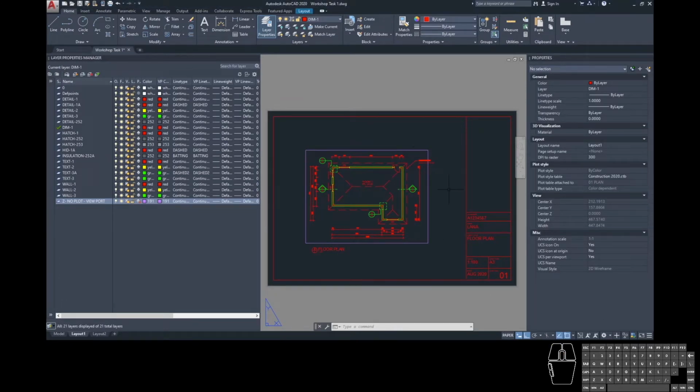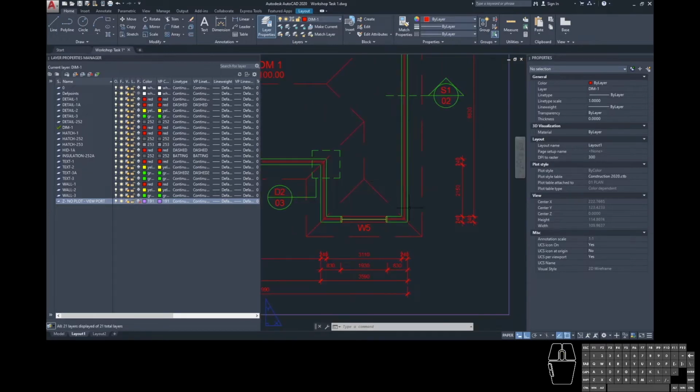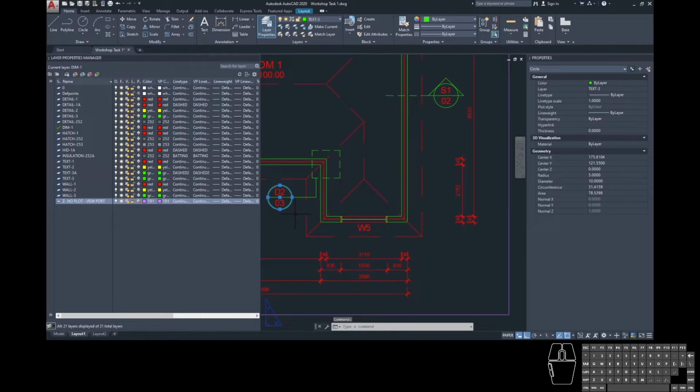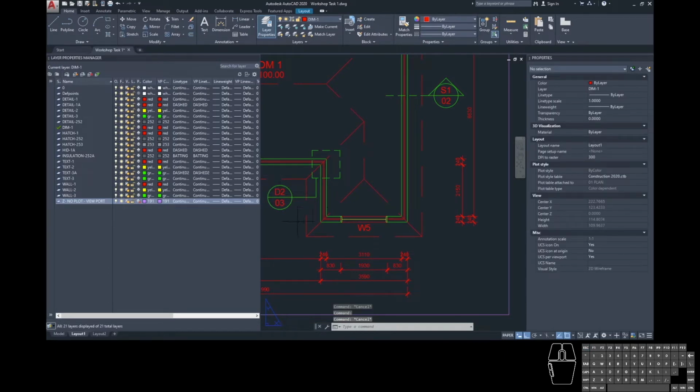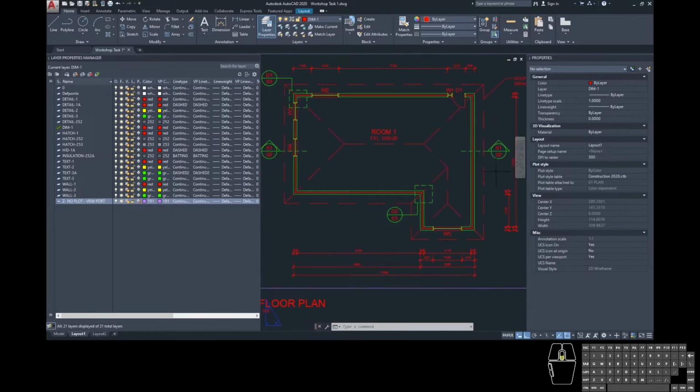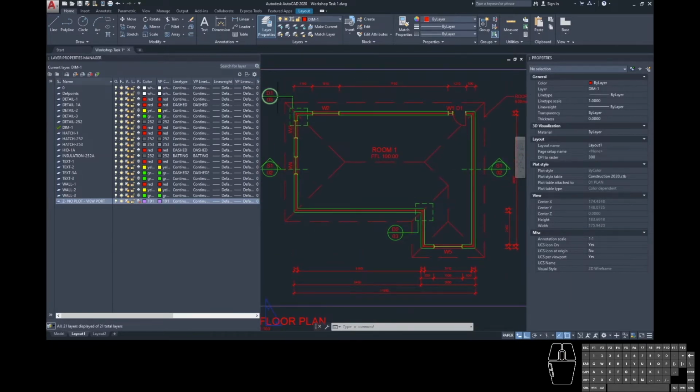What you'll notice as well is that I've finished dimensioning this drawing, and I've finished annotating it, all these annotations that you see on your original hand drawing. These elements are just drawn using circles, which we went through in the first module, and lines, and of course text. So this is just a little set that you can make with the tools that you currently have. It's nice if you make sure that you've got all your circles, they're all the same, and that your angles on these are 45s. Everything is very similar sized and shaped.